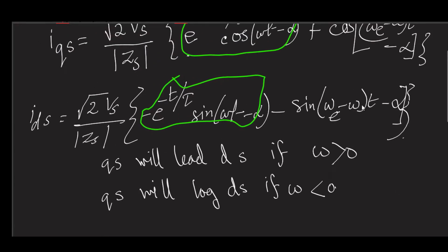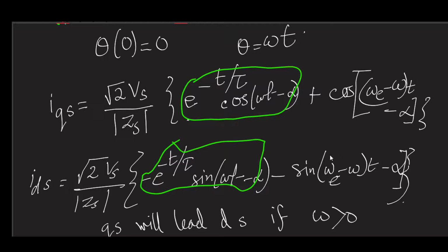Now the second balanced set here, which represents our steady state response, has a constant amplitude with a frequency corresponding to two different angular frequencies of the applied voltage. One is in the stationary circuit and the other is the angular velocity of the arbitrary reference frame. So this difference is between the reference axis and the arbitrary rotating reference frame. Now, if that is the case,